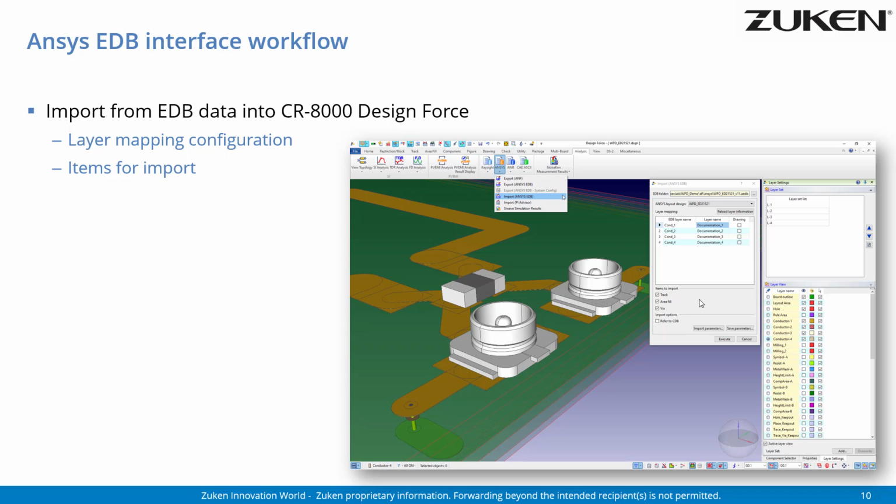An important part of this is the responsibility and authority of what information can be imported directly into the electrical information. For example, the manufacturability and vias will be the domain of the layout engineer, and so any changes in this must be approved by the layout engineers. Hence, it's more often that users will import to a documentation layer, review each change by the simulation engineer on a case-by-case basis, and as they're approved, copy the information from the documentation layer to the conductive layer within the design.